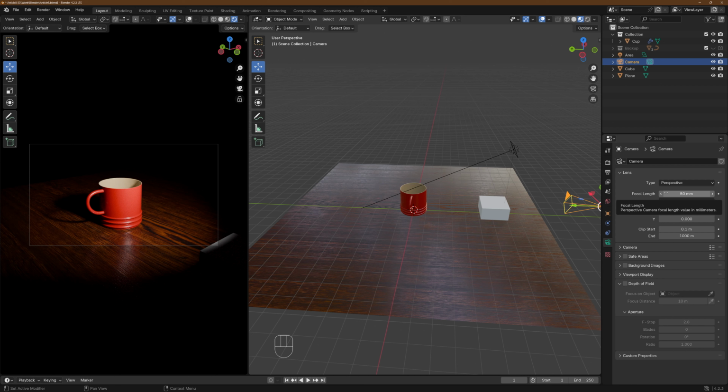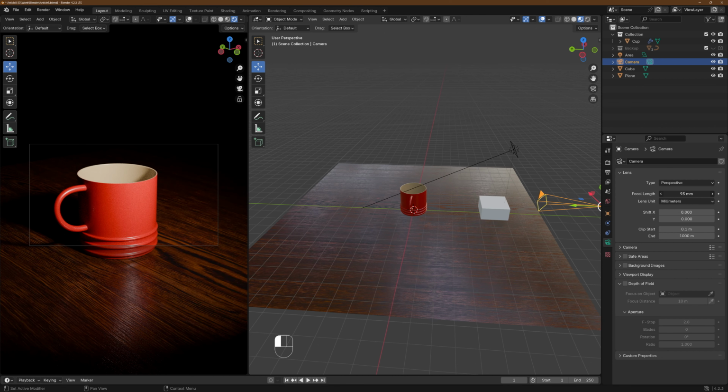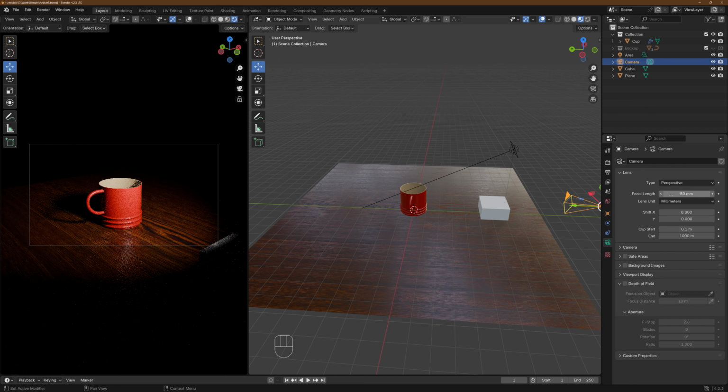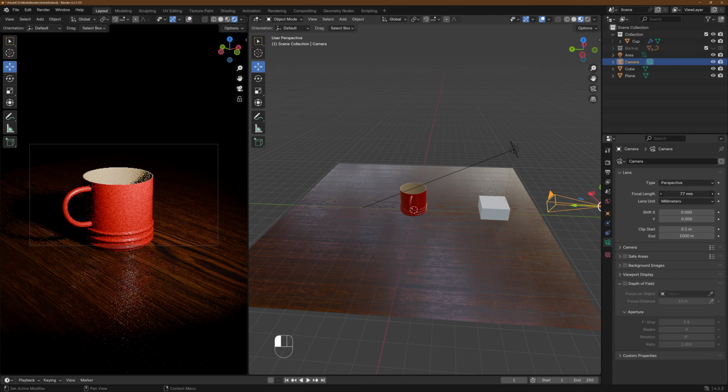The focal length basically controls how close or how far your subject is from the camera. So just imagine it as zooming in and zooming out. Just put it that simply. We don't have to go into the technical terms because you won't really need any of that for 3D. Basically, if you want to zoom into your object, you increase your focal length. If you want to zoom out, you decrease it.